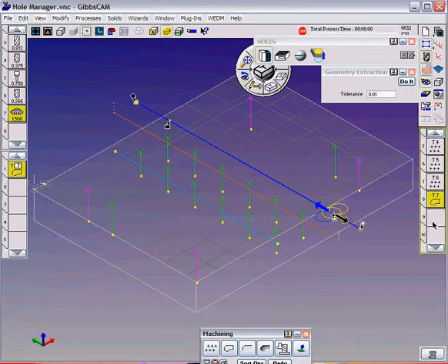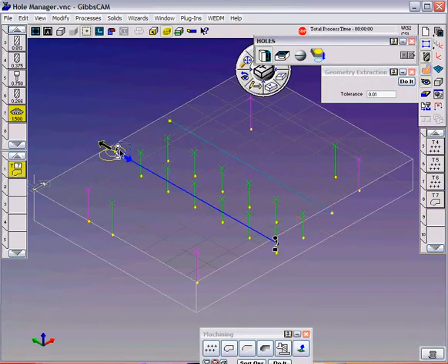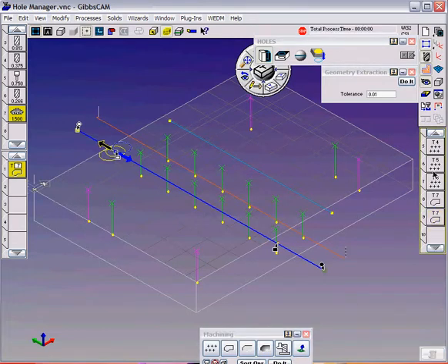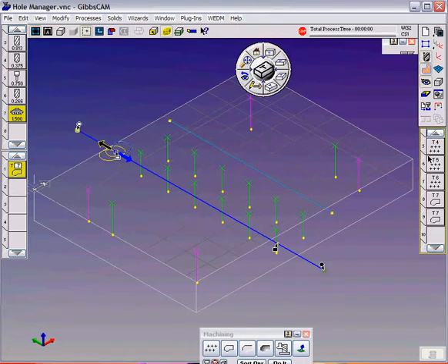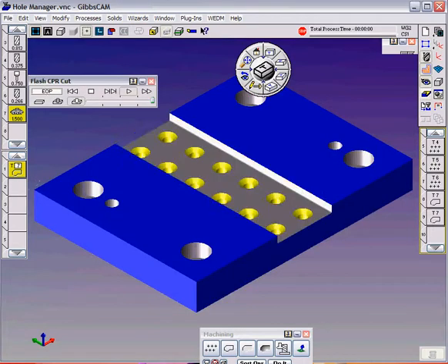Click on the do it button, and since we're climbing going up, you might as well climb going back. All you need to do is click on the other end of the other line, and again, give the tool a little bit of clearance off of both sides of the part with the end feature and start point markers. Click on the do it button and close up our geometry palette. Give us a little bit of room here on this smaller screen, and let's go ahead and render it.